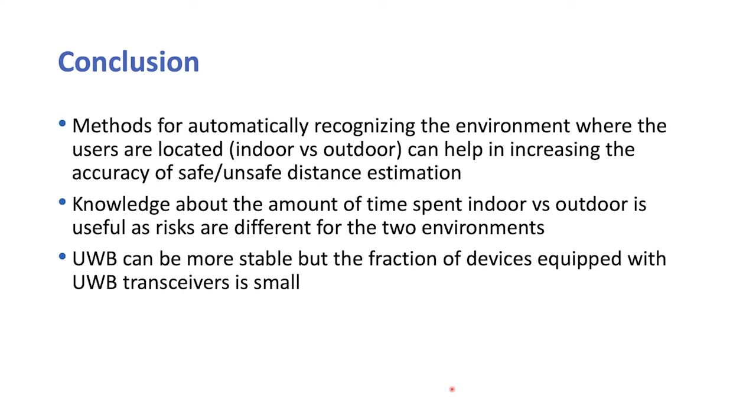And finally, the accuracy that can be obtained using Bluetooth Low Energy is generally lower than the one obtained by means of ultra-wideband. But we also have to say that today the number of devices equipped with ultra-wideband transceivers is quite small. So today Bluetooth Low Energy represents the technology of choice if we want to provide an implementation that is compatible with the majority of devices.